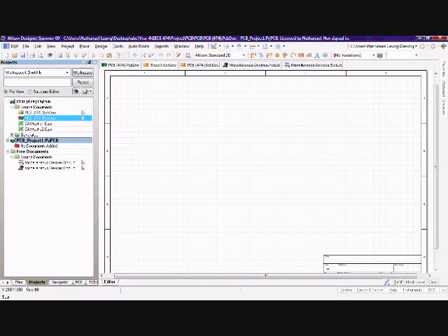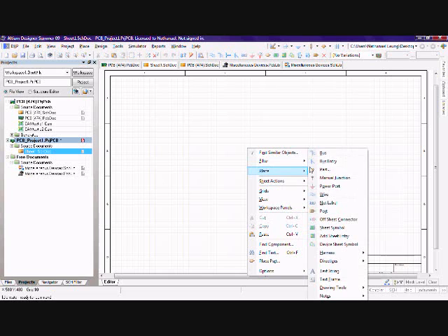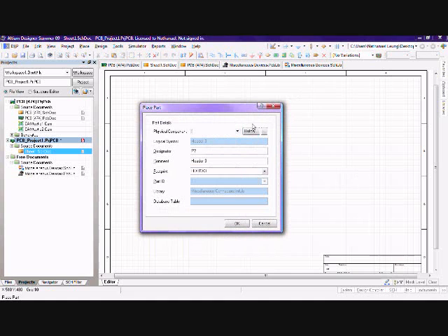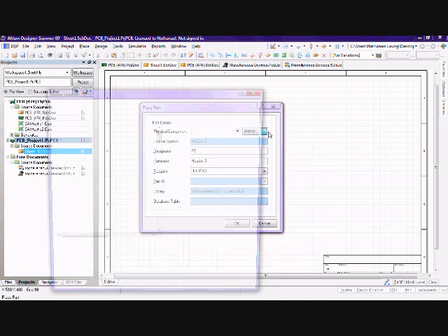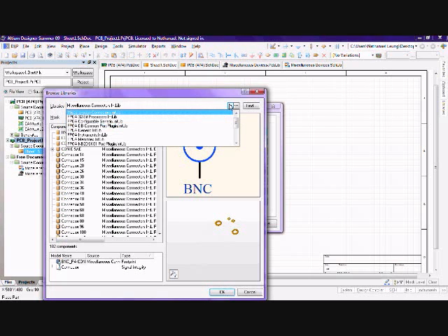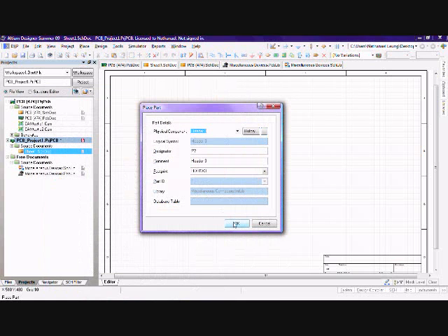In this screen, you will now place each of the components onto here. You press part, which is P, and now you will be given the window where you can choose the parts. You click the ... right here, and in this library section, it will allow you to either choose a device or connector. Now, the component we will use for this tutorial is the IR sensor, which contains 3 pins: the IR, the 5 volts, the ground, and the in. So therefore, we will scroll down on the connectors to 3 headers. Choose this, click OK, and now you will be given a choice to enter this component.